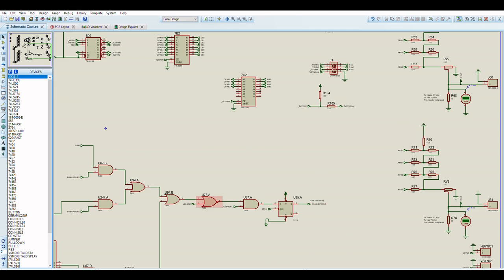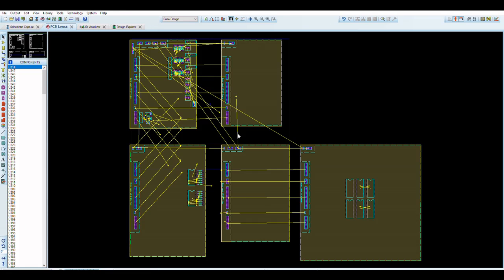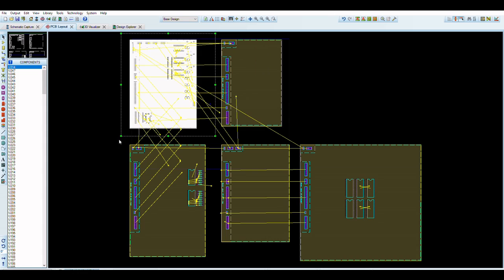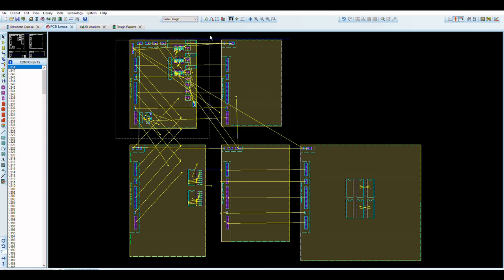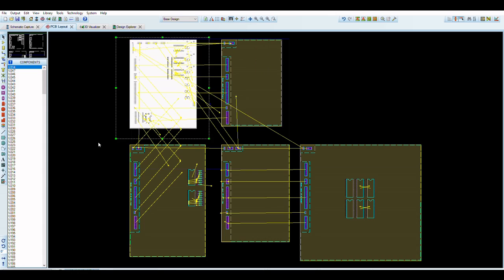So that's basically an overview of all of the original hardware, plus extension tweaks over and above the original hardware schematic. So the next layer is the complex layer, which is the biggest board. This board here has all of the pixel combination logic because it's the video generation board. Video signal generation board plus pixel combination logic sits here.